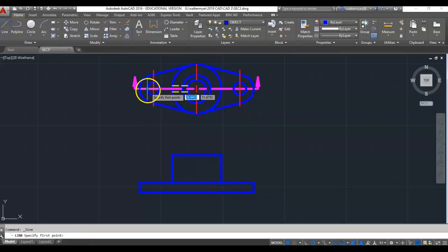I'm going to bring the sides of these small circles down. Again, one side is the same as the other. So I'll just take it, mirror. Again, I'm doing these lines in object because this is going to be cut away so I can see these. Now I'm going to do the counterbore hole here.